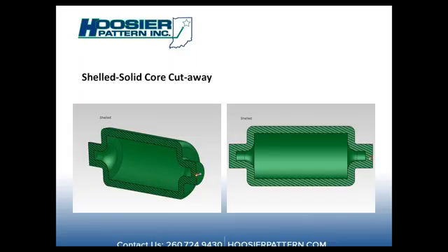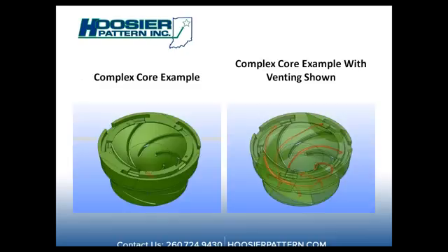The other thing to think about with your cores is the elimination of core assembly. This is a huge time saver and a quality improvement. No more internal fins on a casting. They can be eliminated. And then there's core vents. No more drilling cores to get a vent and having a straight line. Now you can be a little bit more creative and have your vents work for you in the way that they're going to eliminate gas out of your casting and help with the core crush and collapse and disintegration and get out of it in shakeout.